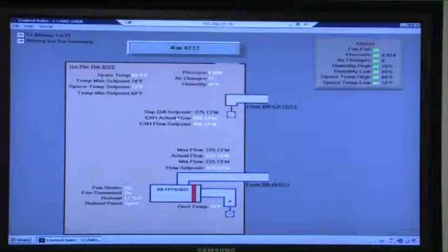Yeah. Alright. So differential set point, it's a negative 275. So exhaust flow is 500. Exhaust flow set point's 496. That looks good. Max flow is 225. Actual flow is 210. Mid flow is 225. Flow set point's 225. So max is 225.